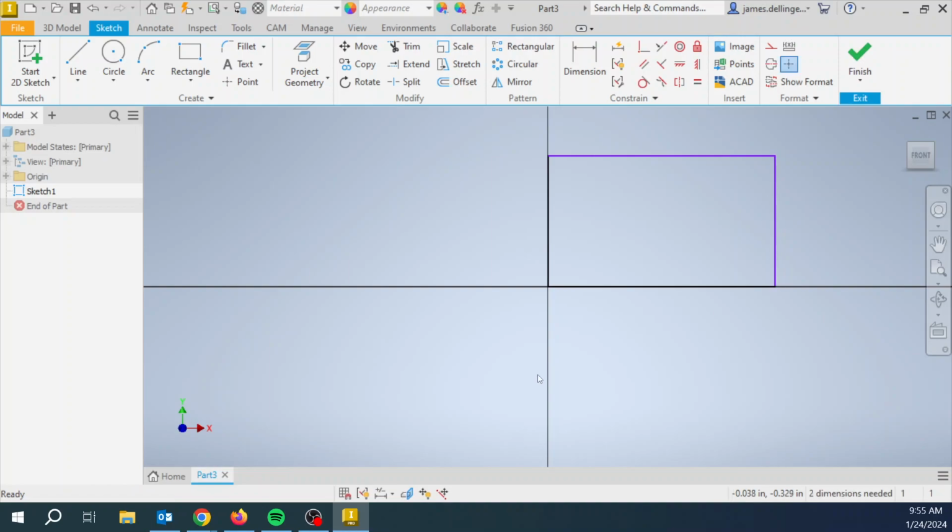by using dimensions, okay? So we want to use constraints, and we're going to talk about these today, constraints to our geometry, all right, and dimensions, right? That's why they're all in this little tab section here, in order to fully constrain whatever we're sketching, okay? In this case, we're going to use dimension, right, to say how wide this is and how tall this is, okay?